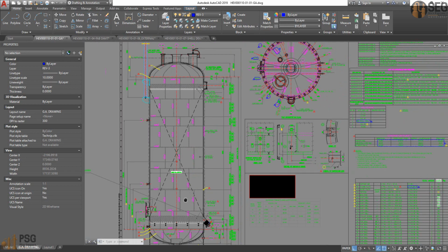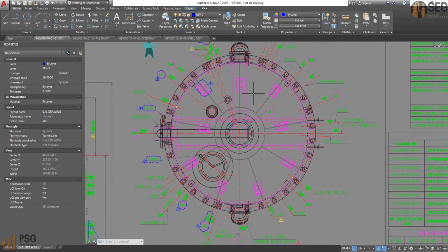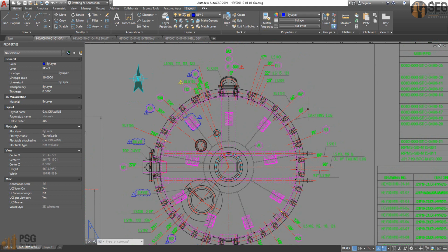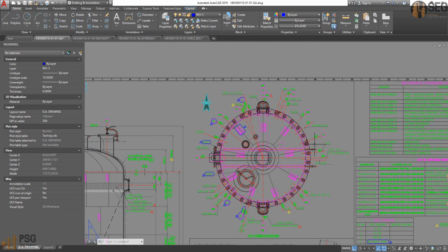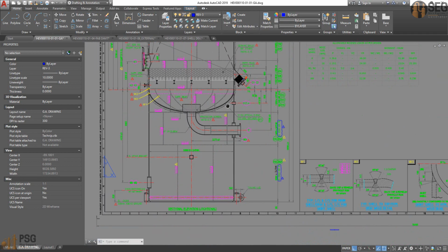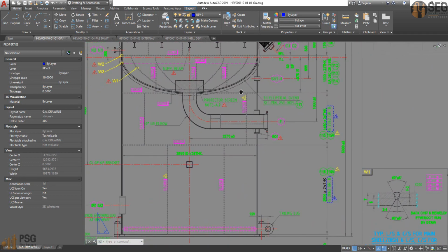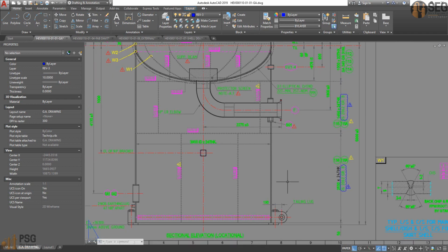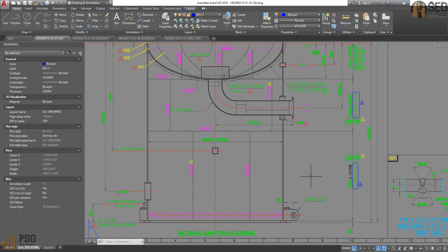And if we take a look at the top view, we can calculate the number of segments on the top head, and from here we can get the orientation of the longitudinal welding lines. Here on the support skirt, you can see that in this skirt we have 3 cans. Here is the first can length, thickness and material, and the information for the second can and third can.